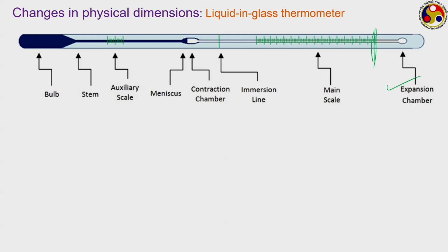So, there are several possible liquids that can be used, but the most popular one definitely is the mercury thermometer, which can operate over a range of -38 to about 350 degrees Celsius, because mercury starts to freeze around -38 degrees Celsius and its boiling temperature is around 350 degrees Celsius. While the boiling temperature is more or less okay, the freezing temperature is quite high compared to several